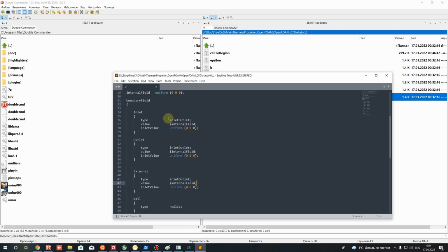This boundary means that we don't have a fixed value of inlet velocity. The velocity is defined by the propeller working. It means that if a propeller requires much mass flow, this boundary returns the mass flow which will be transported across our propeller.